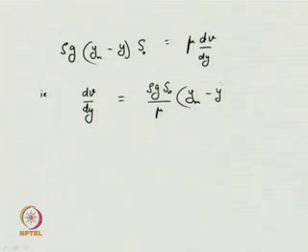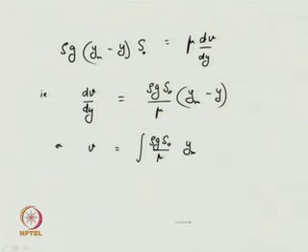(ym minus y), or you can use this relationship now to obtain the integral, say v, the velocity in that small portion of that overland flow. It is nothing but integral of rho g s naught by mu (ym minus y) into dy.